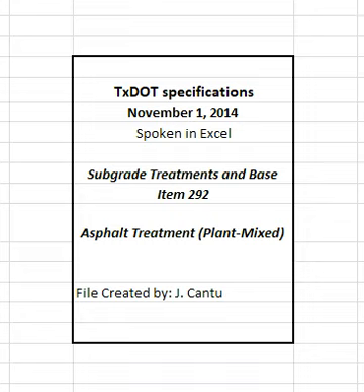The department will not perform any tests or assume any liability for the quality of the department-owned RAP unless otherwise shown on the plans. The contractor will retain ownership of RAP generated on the project when shown on the plans. Fractionated RAP is defined as having 2 or more RAP stockpiles, divided into coarse and fine fractions. The coarse RAP stockpile will contain only material retained by processing over a 3/8 inch screen or 1/2 inch screen unless otherwise approved.